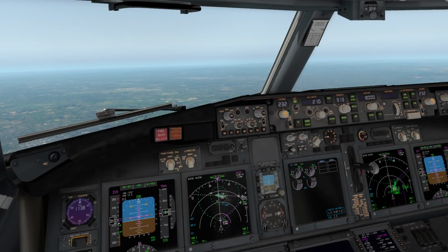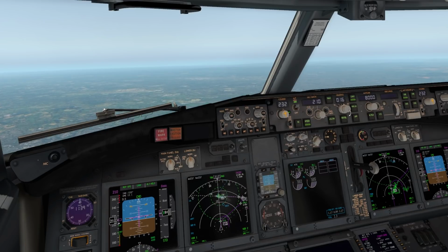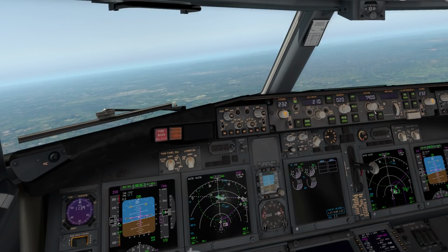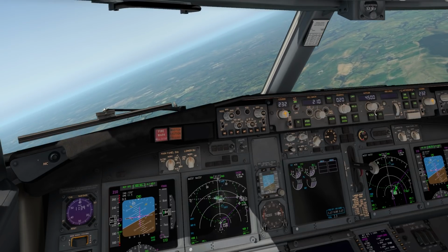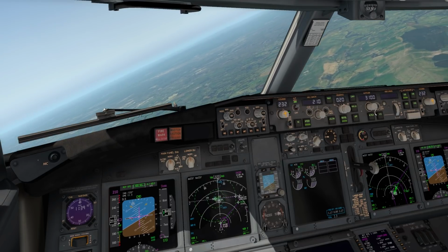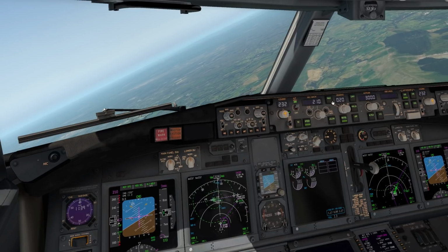So we're currently inbound to Dane. We'll imagine we'll advise Manchester radar we're ready for the approach, and we'll just imagine they're giving us our initial vector onto the ILS approach. Turn right heading 020 degrees and descend to 3,000 feet. We'd also tell them we'd want a slightly longer final just to get established nice and early. Again, we'll cover the guidance with how we're going to fly this approach shortly.